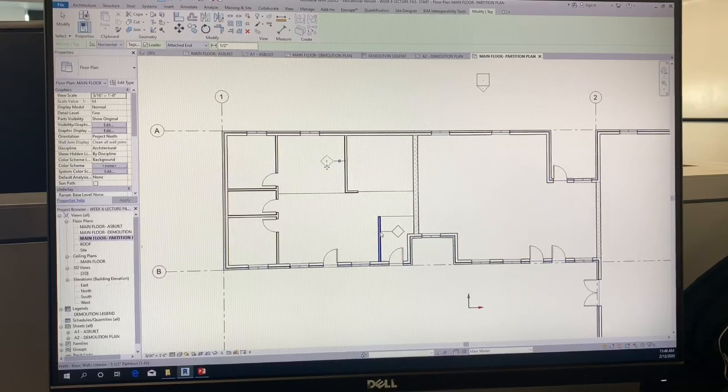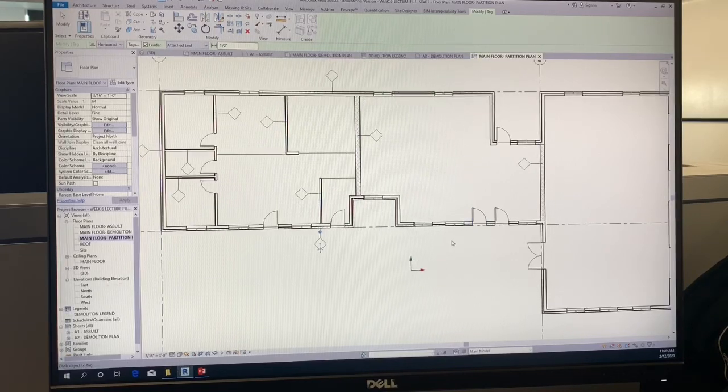I'm going to tag this wall. I'll tag this wall, this wall, as well as this wall. Now, I'm not going to tag this whole wall. I've already tagged it up here, and I don't need to tag it down here. This is a continuous wall right along here. I'll tag this wall. This is a new wall type, or different wall, so I'll tag that wall. And I'll tag some of the exterior walls as well. Again, I'll only put one tag on each side, and I'll put a different tag if it is a different wall type.